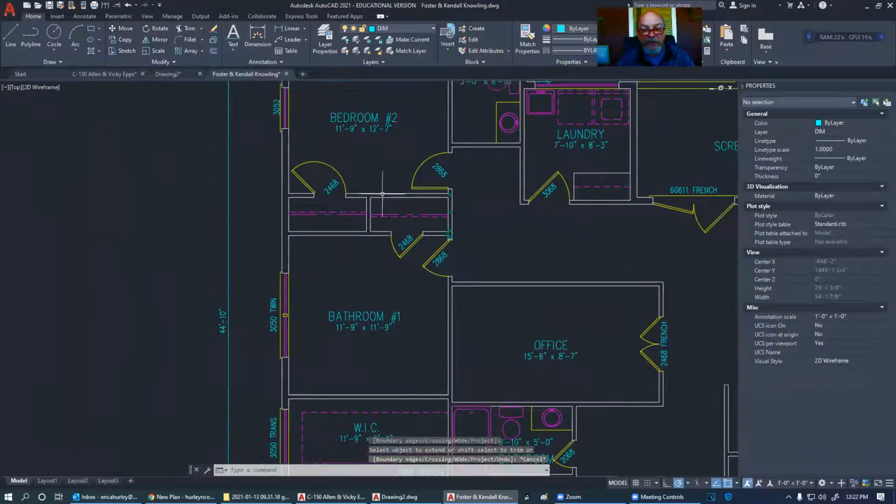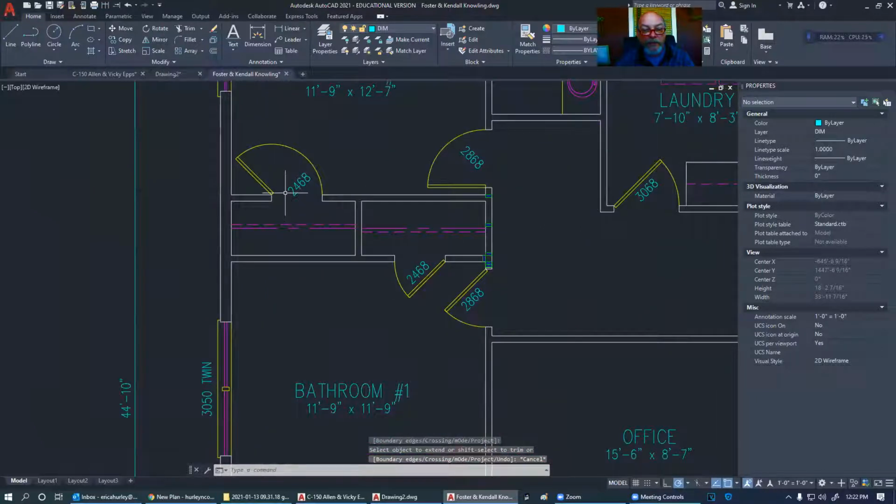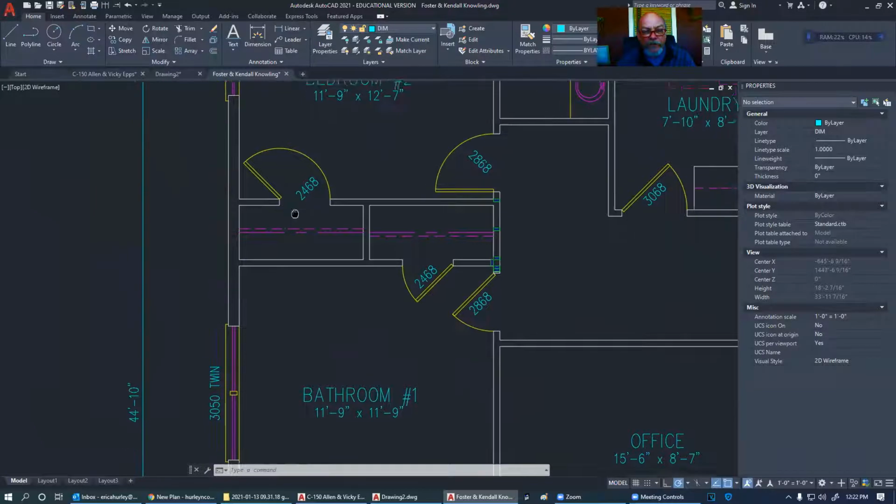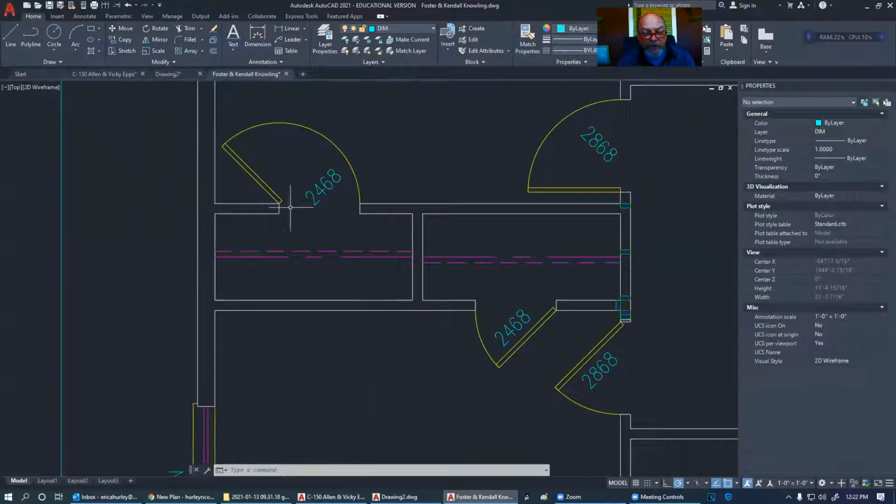Look how much space this took up. This is a smaller door by 4 inches, but look how much space it took up here because it's so far. Now, why do we not stick it way over here? Well, because of what we can access as humans on the inside. We need to put this in the center of this closet so we have equal and easy access to both corners of the closet here.